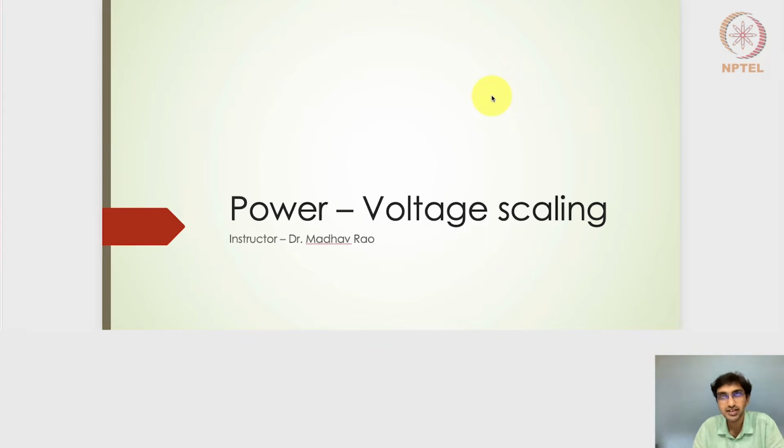So what generally goes in a digital designer's mind is, if I want to save a lot of power, let's use a lower voltage rail. But at the same time, if I want to get a higher performance or a lower amount of delay, then we will choose a higher rail or a higher VDD value. For a particular digital design, we need to cater towards the power benefits or the power savings, and we also need to cater towards maximizing the performance benefits.